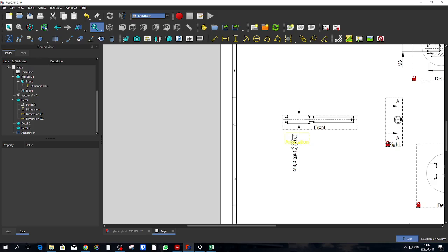By adding a circled E, what you're saying is if under maximum material conditions, so if it's at its maximum size, which is 5 micron less than 8 millimeters, it must be perfectly straight. If it deviates from the maximum material condition, so if it goes smaller, then it can have imperfect form as well. Alright, but specifying this means we specify the straightness and cylindricity of that part of the pin.